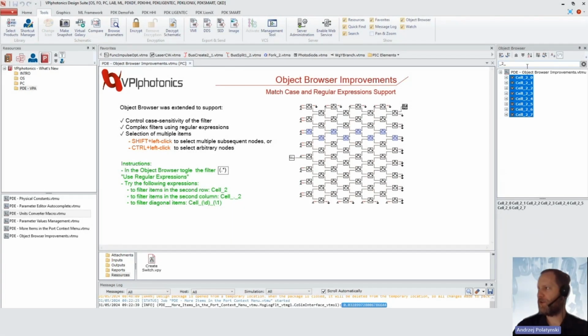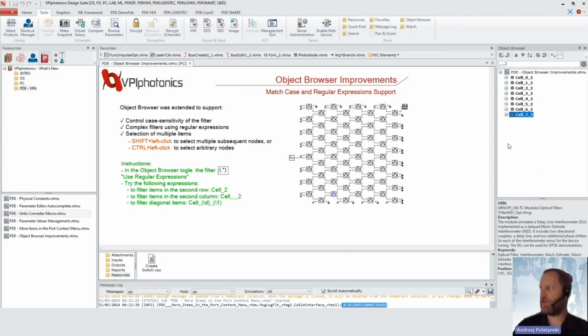If you would like to use some more complicated structure, it's also possible to use a so-called regular expression. If you would like to get the structure of only the second columns of the second rows, it will be much harder, because if we specify only _2, you will see that along with our _2s, we also find the previous ones. But what we can do in that case is specify an additional structure where we are defining the expression. In that case, dot means that there should be some other value placed there, and we can very easily select only the structure there.